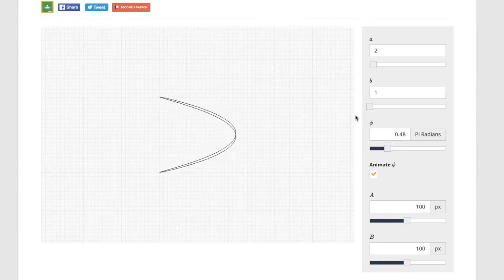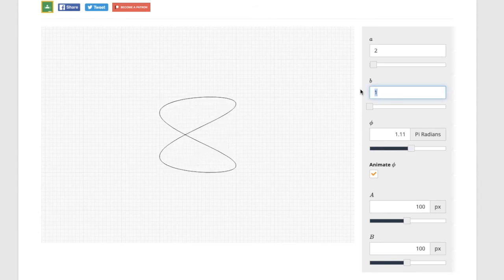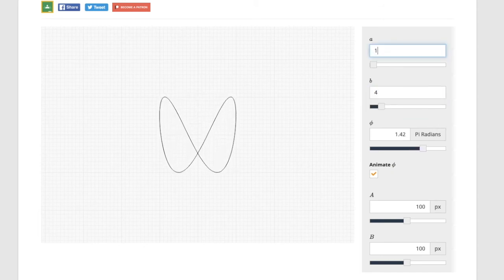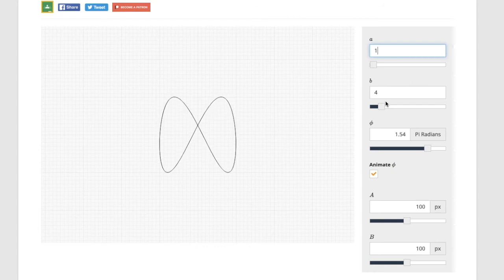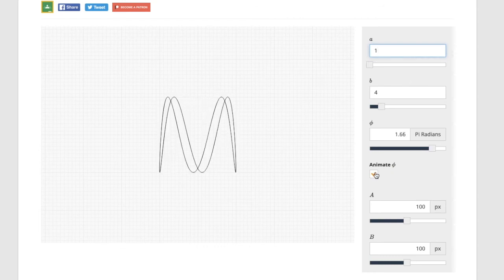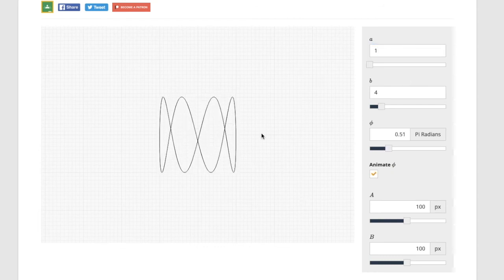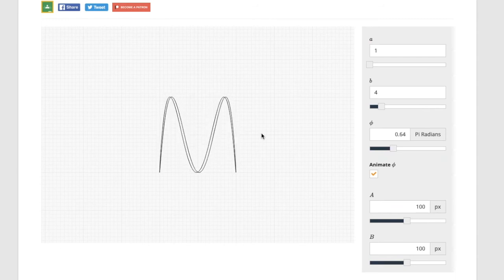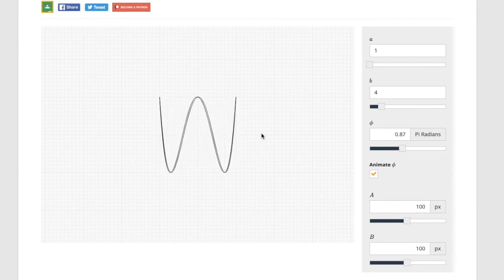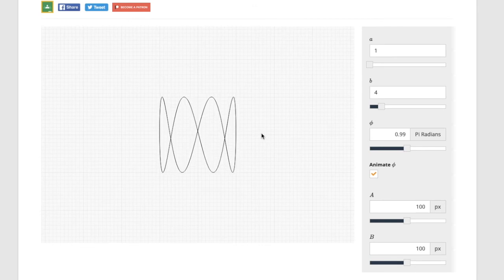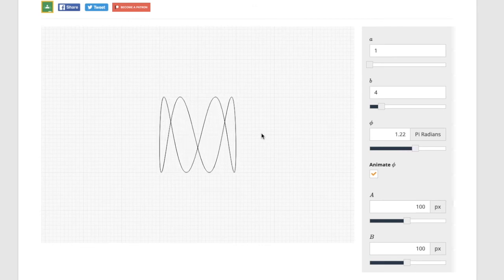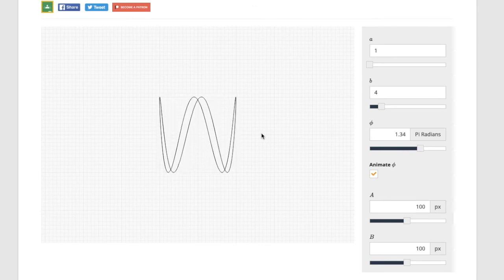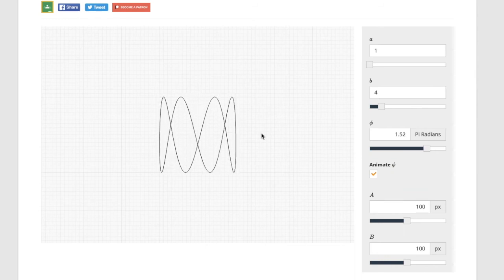is along the horizontal. And if I assume that signal 2 has a frequency of 4 Hz while signal 1 has a frequency of 1 Hz, meaning there's a ratio of 4:1, let's see what will happen. Notice that the pattern changes as if there is a presence of 4 continuous parabolas rotating along the vertical axis. So this is what we call a Lissajous figure or Lissajous curve, and it has many applications, but I'm going to focus on the most practical one.